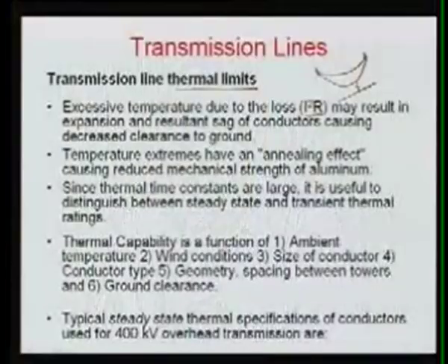But if the loss is more than the dissipation of this loss, that heat. If less, then what will happen? The temperature of the conductor will keep on increasing. Once it keeps increasing, then we will have the expansion and the sag, and that is very, very dangerous.